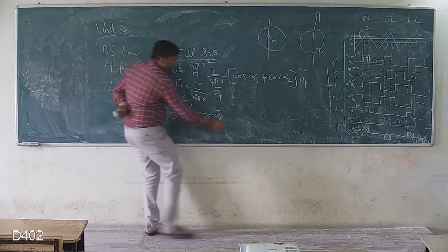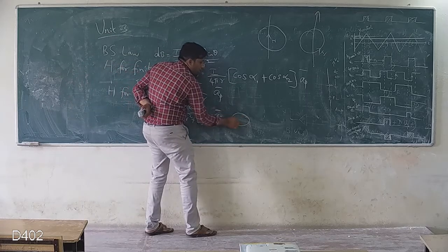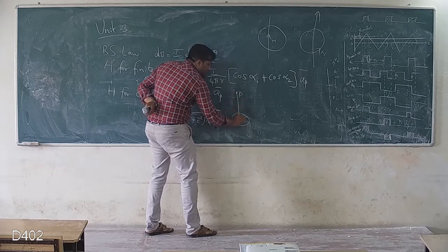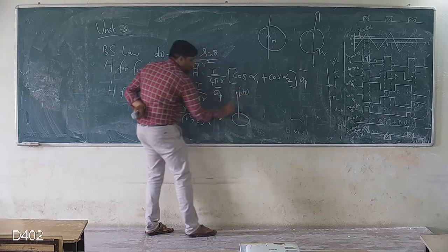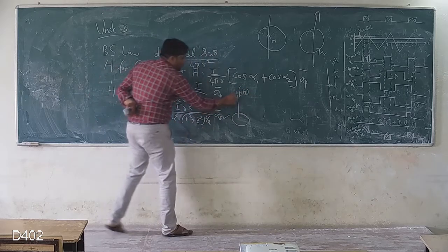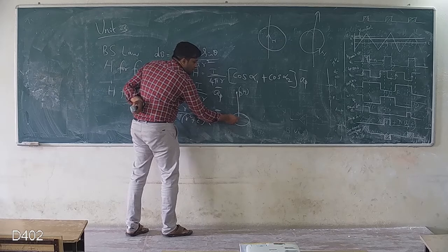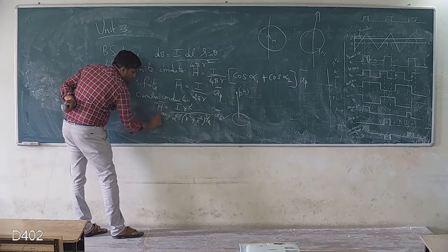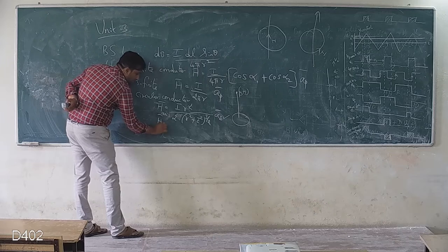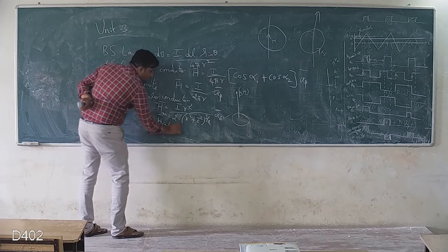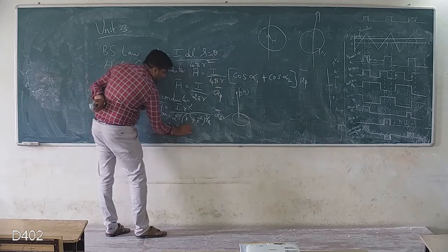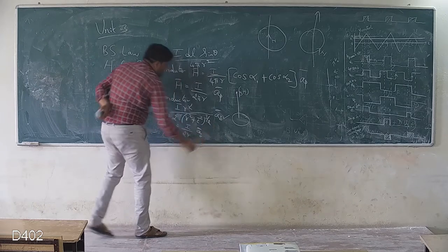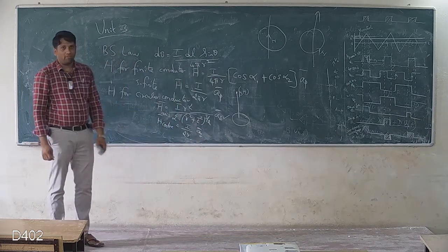This is if I take a circular conductor and place a point capital P away from it, and find the H there. Suppose P is dropped down to the center, on the axis. H vector at the center, if I put z equal to 0, I will get I divided by 2R as the answer. So that is the third set of problems we have solved.